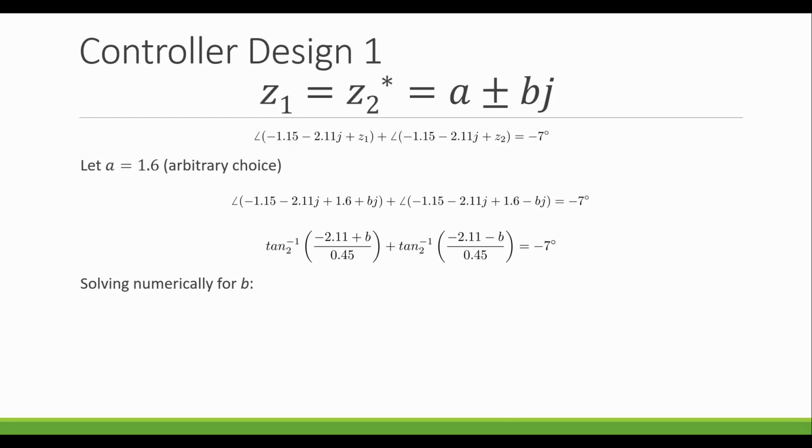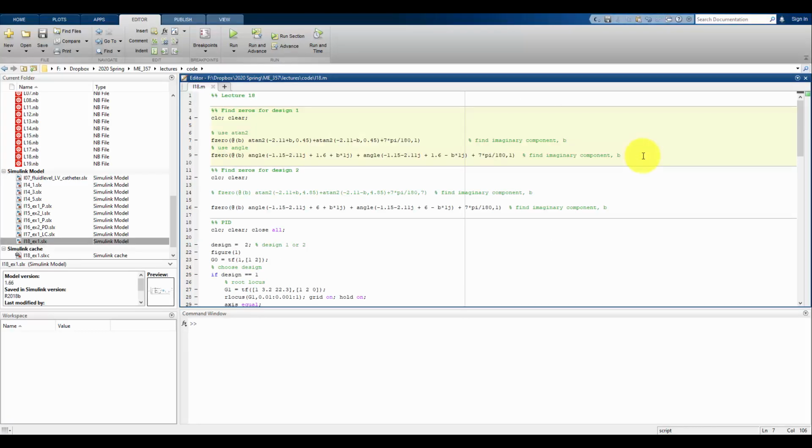And to do that, I'm going to take this equation and put it into MATLAB. So I can express that equation 2 different ways in MATLAB using the arctan2, or in MATLAB, I prefer to use the angle function because I can have real parts and imaginary parts. So I show on line 9 using the angle function, but I'm also showing here the same thing if I wanted to use arctan2, but then I have to put in manually what the imaginary parts are as the numerator and what the real part is as the denominator. So let's look down here first.